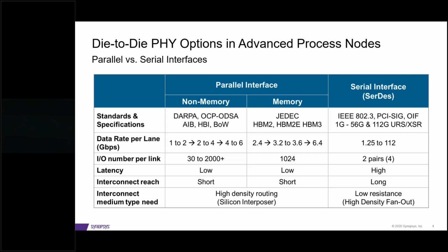My analysis so far, from a presentation I did on Tuesday at OpenPOWER about the Open Memory Interface, which is just a slow 25 gig transceiver interface, with 8 lanes times 8 channels, is that it actually takes up the same amount of die area as an HBM. And not only that, obviously you don't have the packaging problems because you can go to a lower density.